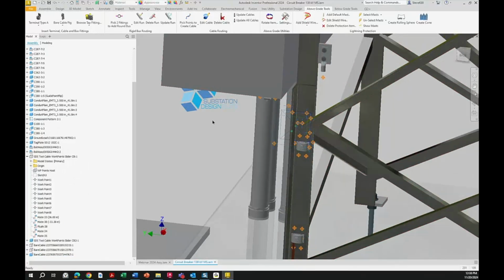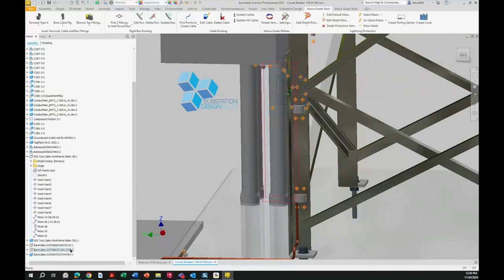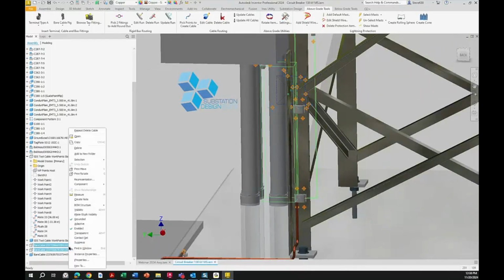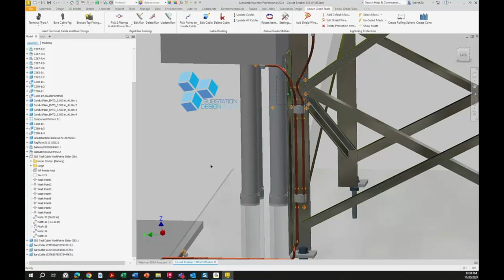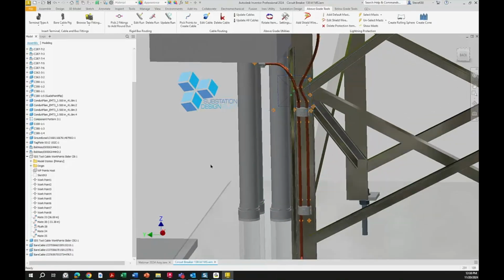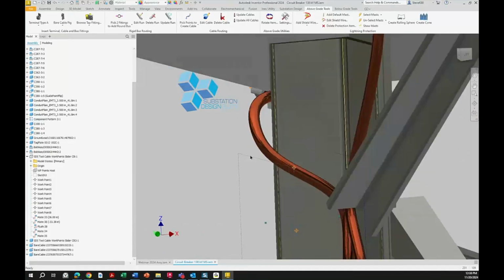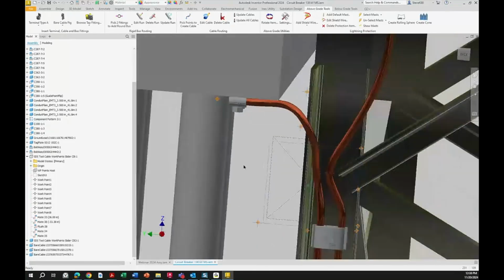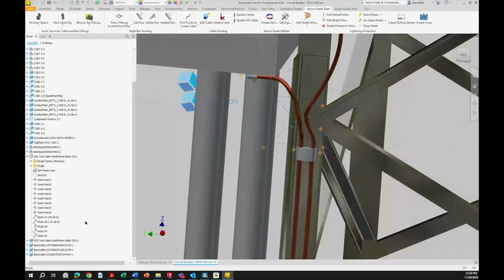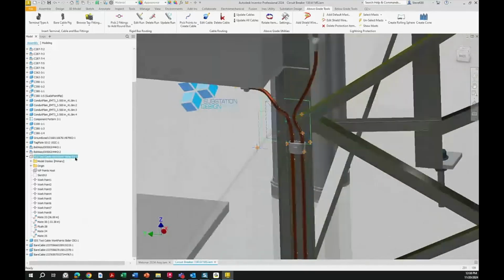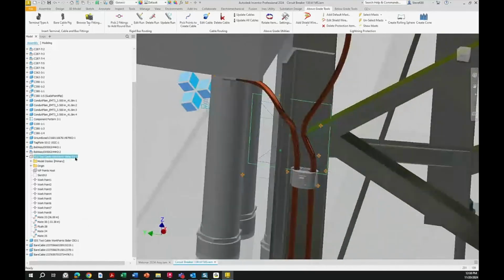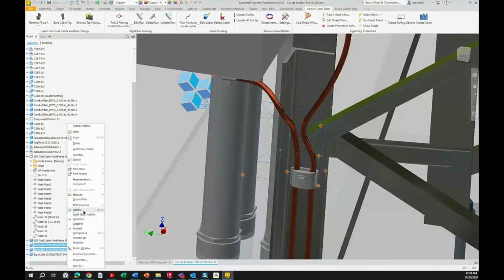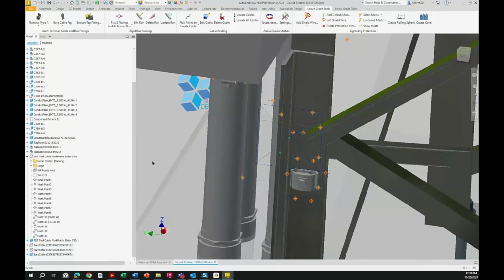All right. So I'm going to turn on these cables that I have turned off. Visibility. And you can see that what I did, I picked work points so I could bend around here. All right. So if I come in and I'm going to edit this slider tool, and I'm going to look at, well, why don't we turn these off again? I'm going to turn these guys off again. I'm going to run a new cable. All right, so let's run a new cable.